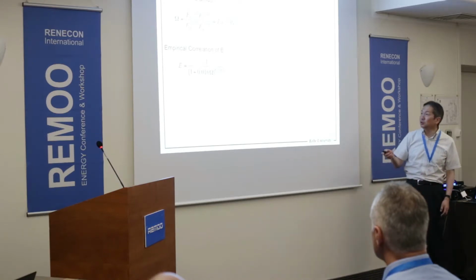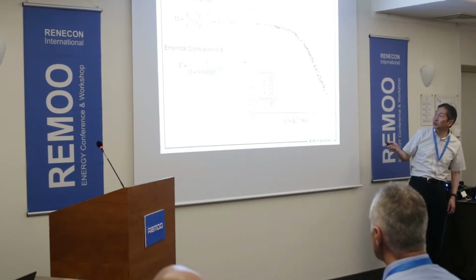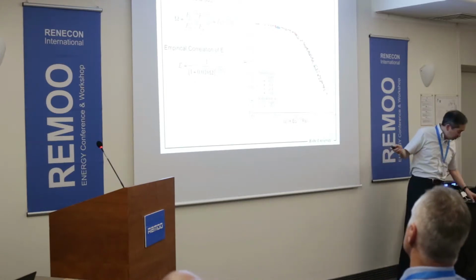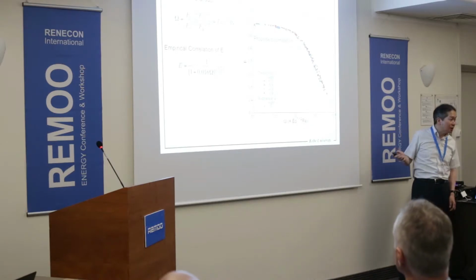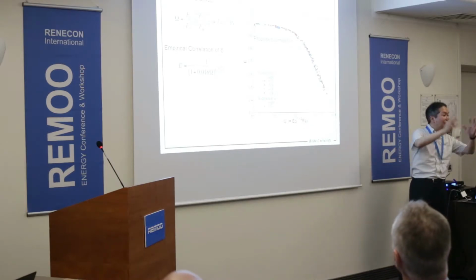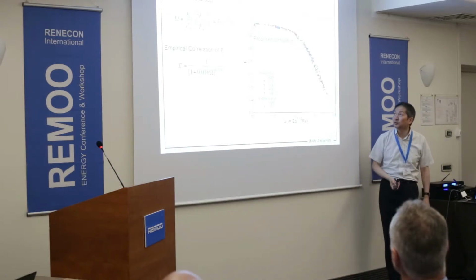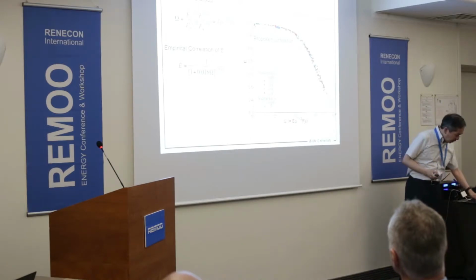correlation. Eventually, we found that if we use these dimensionless groups, all the data, including air-water data, collapse on a single curve like this. Okay, and using this very simple empirical correlation, we can obtain this kind of agreement, so that for the single bubble in a very quiescent system, it's okay to use this kind of correlation for ellipsoidal bubbles.